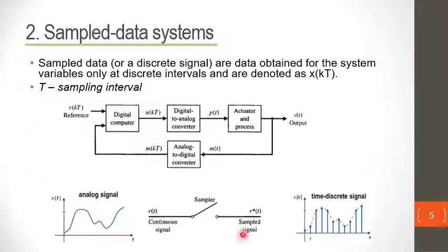And what's important to note is that the sampling time can change. Sometimes you can sample slower, at a rate of 1 second, and sometimes you can sample much faster, at a rate of each and every half a second. And this will change the nature of the control system that you have, generally speaking. Later you will see it can affect the stability of your whole control loop, depending on how you change your sampling time.